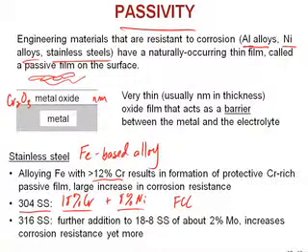Interestingly, if we want to make a stainless steel knife, we don't want to make it from a face-centered cubic structure. We want a knife to be very hard. We don't want a knife to have a lot of slip systems that can be ductile. We want the knife to be hard, so it isn't austenite.